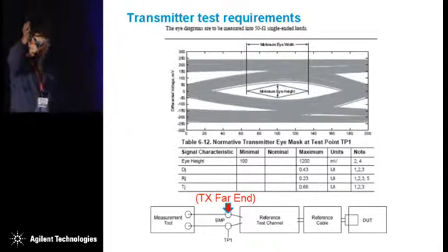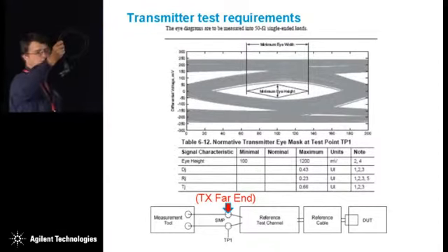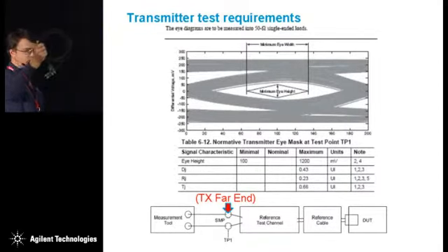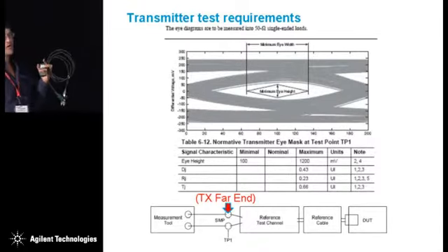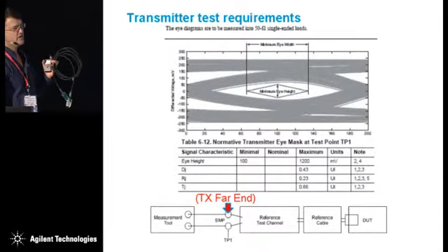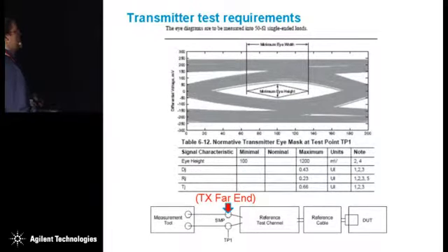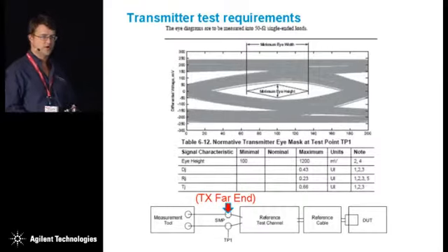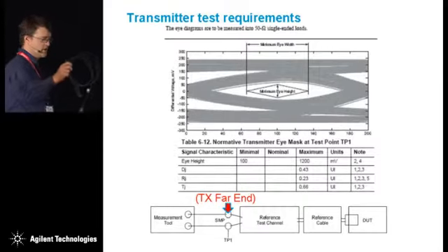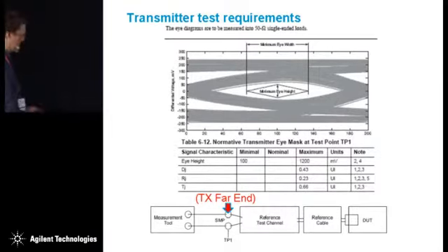So this is the compliance channel defined by the USBIF for certification of hosts and receivers. So we physically measured the signals at the far end of the channel and said, yes, this is the eye stress that we want after equalization at a receiver for a compliant transmitter. And then we measured that channel with an ENA and created these S parameters of this channel that we will show you embedded into our transmitter compliance application.